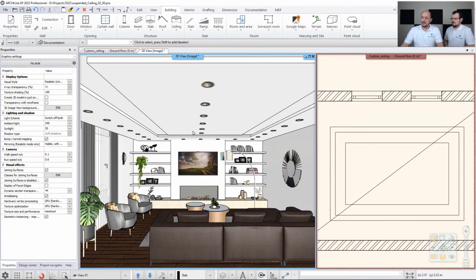With these tools we created this little panel inside the ceiling of the room. Also, as you may already know, the ceiling tool supports other light sources like spotlights that you can nest into the ceiling. And using the LED strip tool, you can also design the LED strip inside that part that you have designed in the software. So this is how flexibly you can design a relatively complex suspended ceiling in a relatively short time with these tools. And if your design changes at any time, you can fine-tune the shapes using the 2D profiles. Yes.